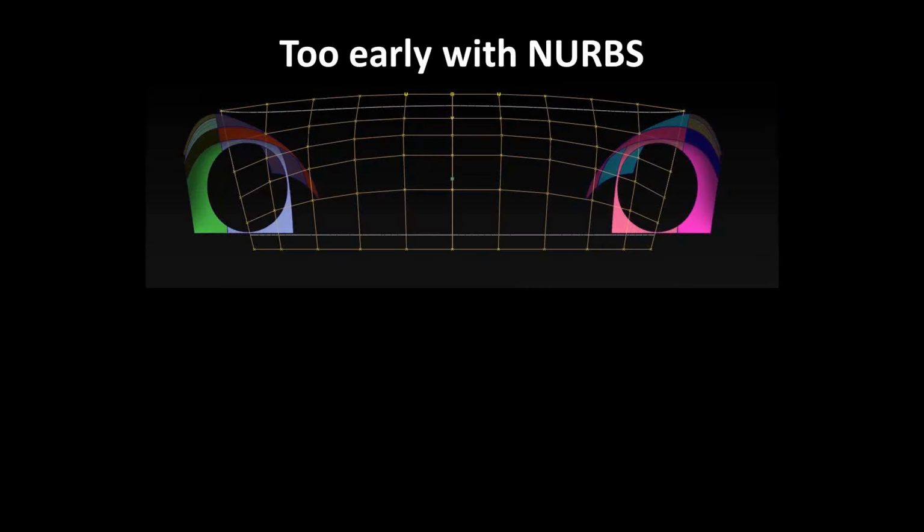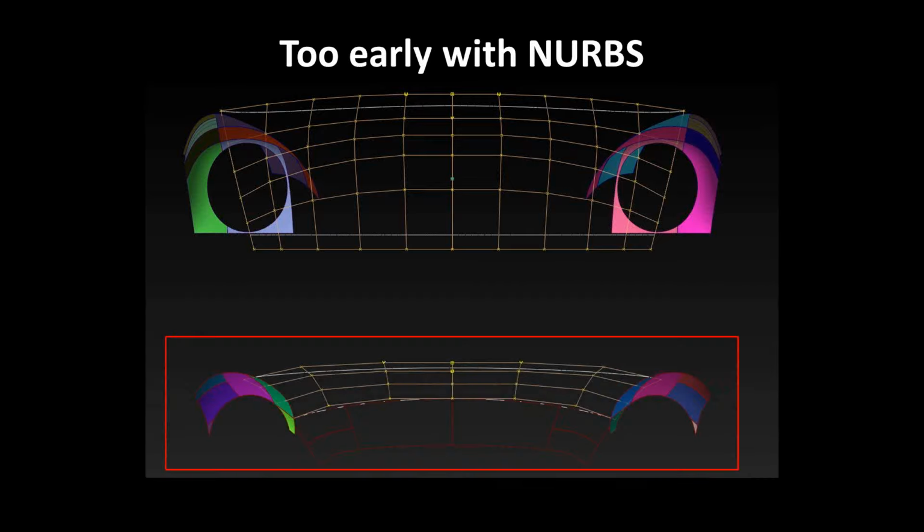Of course, you don't have to do it like this, but I want to show you a risk. I have here a result from somebody who started too early with NURBS. In his mind, he put the basic volumes into place, and then he immediately started to surface them without having, and seeing, the volumes. He did a hood, which I show here with the control point pictures, in a way that is not appropriate. I show you right now how the surface model should look. You see that the hood in the final surface model is way smaller. This is a major problem that can occur when we don't take care to cover the basic volumes with surfaces. Surfaces are like a curtain or something like that. We just cover them.